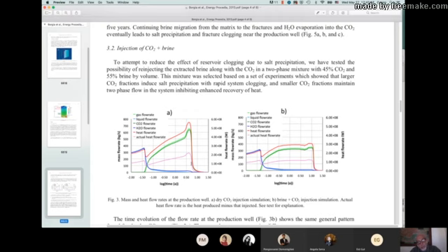So this kind of model predicts that very soon, if you dry out your system, you are going to clog it. The ideal is to actually run it with a little bit of water, not a lot of water, with a tiny little bit of water, so your salt cannot precipitate and cannot clog up the system.